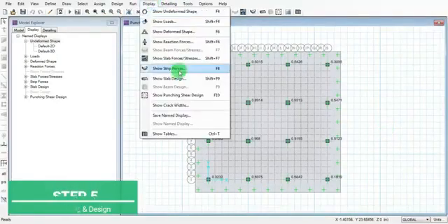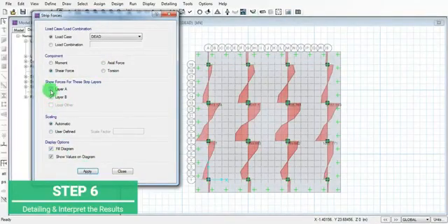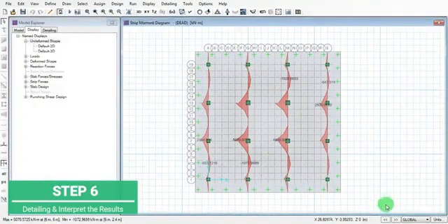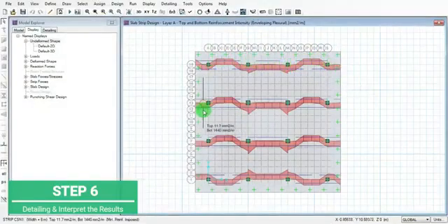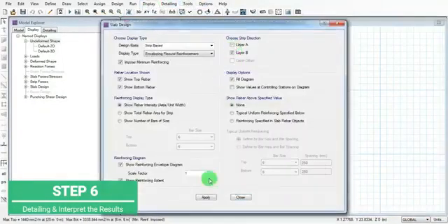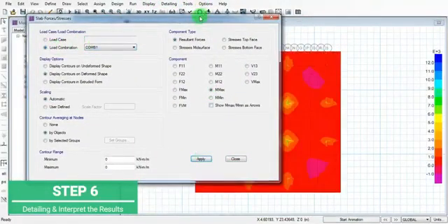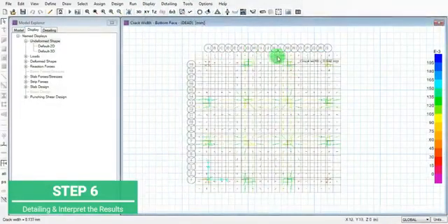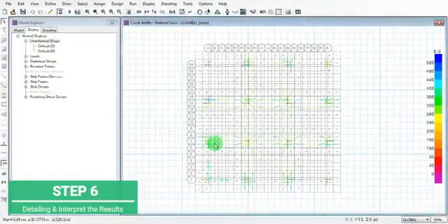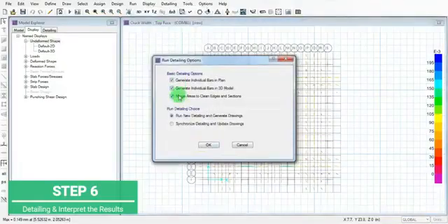Now the next part is to view the different load combinations in detail. Before that, check the forces and all in layer A and B. Now get the imposed reinforcement. Now similarly in layer B for load combination A. This is the crack width values for the slab top and slab bottom. These are minor cracks. Then start the detailing option.